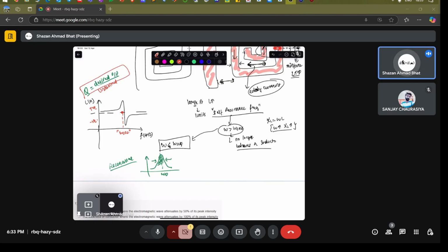When you plot the quality factor in these systems, you see the quality factor reduces beyond a certain frequency. That frequency is again called the self-resonance frequency. So the domain in which you want to make the inductor work should be this particular spot. This is the sweet spot where you want your inductor to work. This frequency range will be best suited for your inductor, so that it behaves as an inductor and does not create other parasitic effects. It should not go into the high frequency regime beyond the self-resonance frequency. These are certain characteristics of the inductors used in microwave devices.